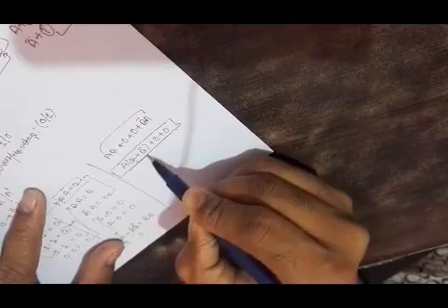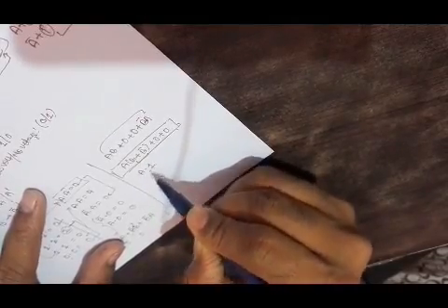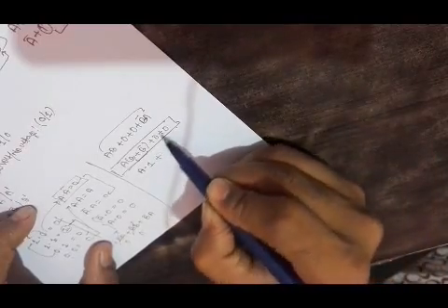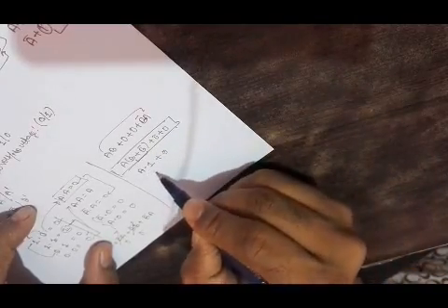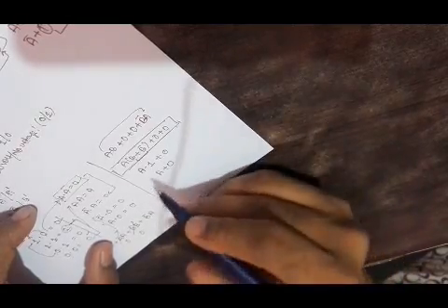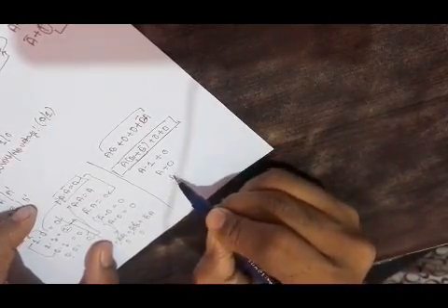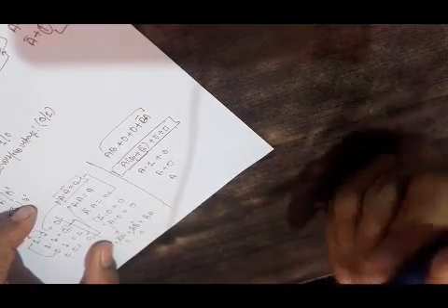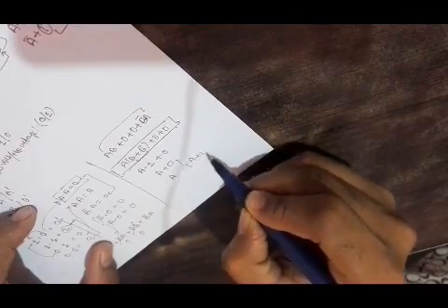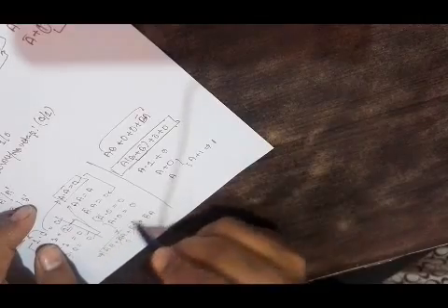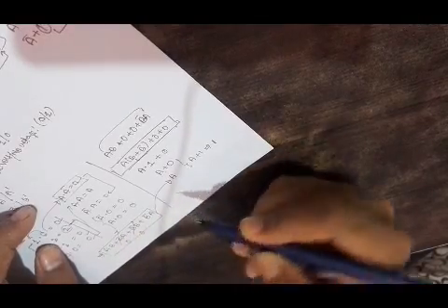So if we apply the above OR operation over here, we have B plus B bar, that will be equal to 1, so A dot 1, and we know that anything multiplied with 1 is itself, plus 0 is nothing but 0. So this will become A plus 0, and we know that A plus 0 is A itself. Addition of A with 0 is A, right? However, if it had been A plus 1, then the output would be 1. Clear? So the entire logical expression will get simplified to A like this.